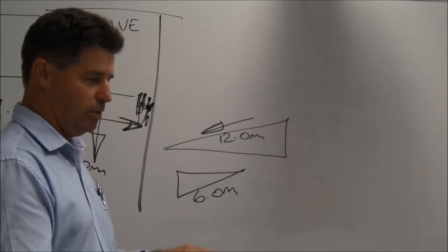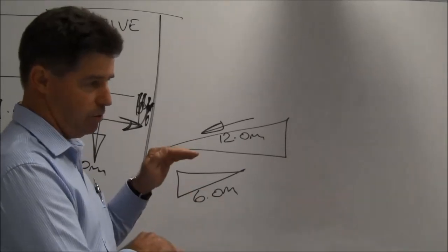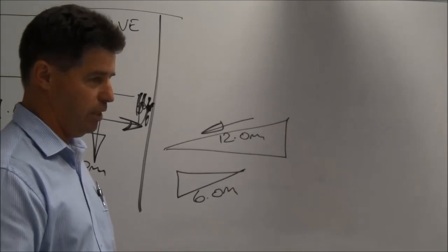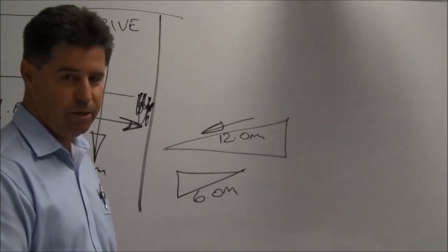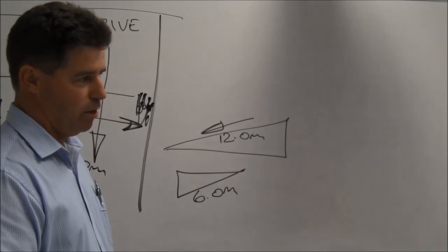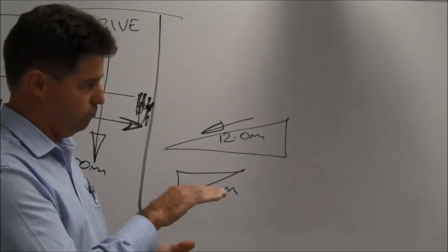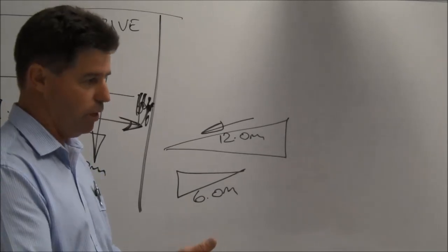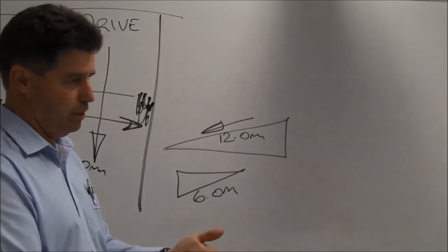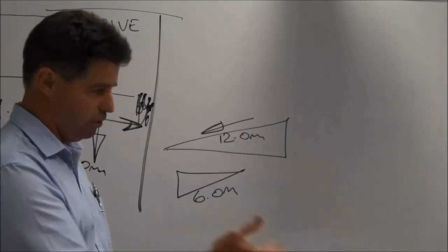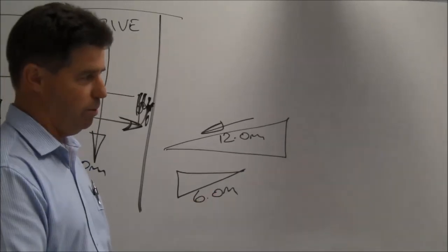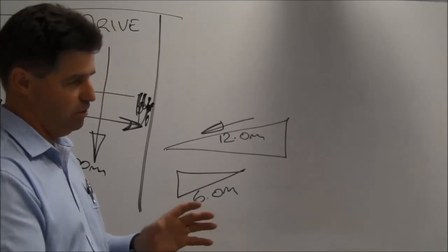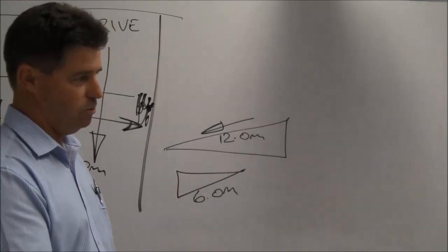As long as you can, because that's out of the Plumbing Code of Australia, out of the BCA. And that's Australia-wide, not just Queensland. The BCA is the Building Code of Australia. If you read through Volume 3, it says some states, like Queensland, have things for stormwater. It basically says they've got their own requirements, which is QDM. So as long as we follow QDM and it says we can do this, councils will accept it.